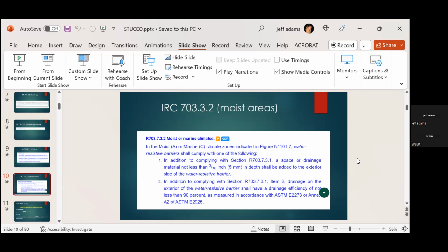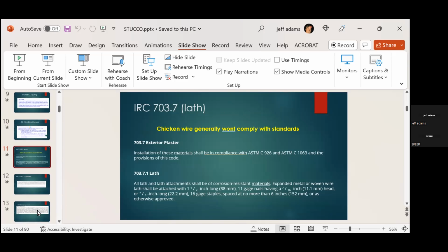Great way to control the moisture, allow airflow, dry by evaporation. But the other thing I really think we're going to see as a byproduct of that is way better energy efficiency. We're going to break a lot of that thermal bridging that occurs as that southwestern side really heats up and transfers that heat inside the house. I think you're going to see a major difference in that thermal bridging.